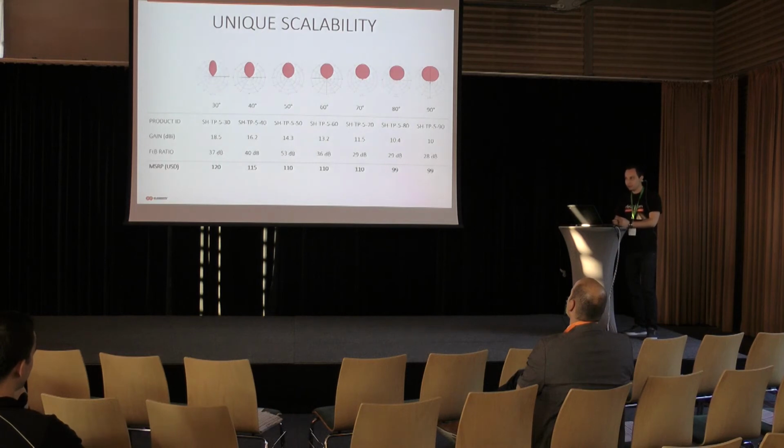Your gain, first of all, is lost when you are connecting the radio to the AP, because you are using pigtails, and even the best pigtails in the market have a loss. So of a 20 dBi antenna, you will never get 20 dBi. Forget it. It's impossible. It's physics.